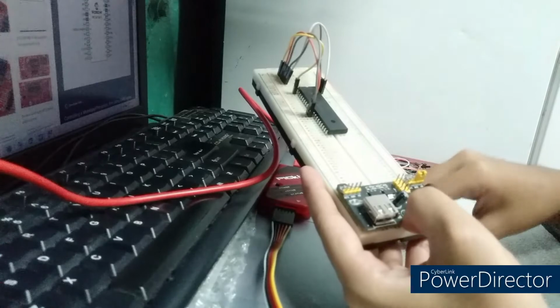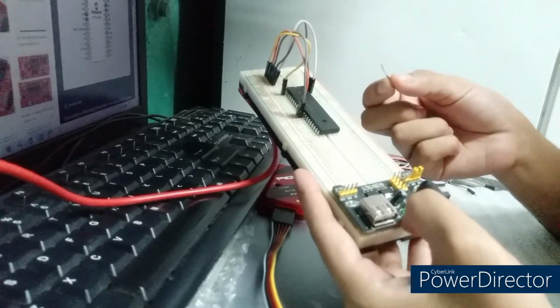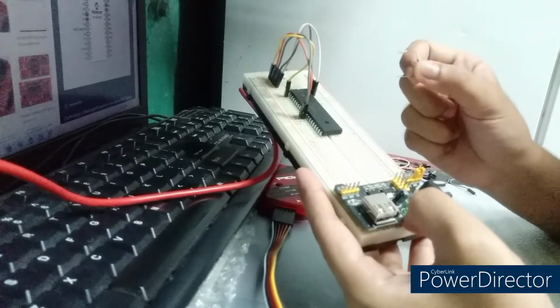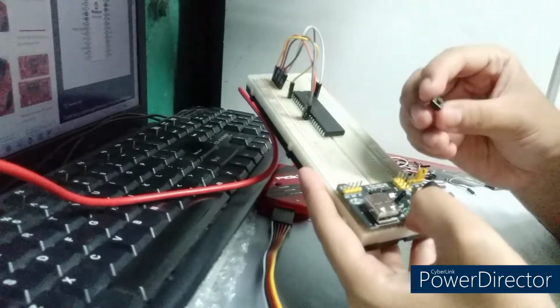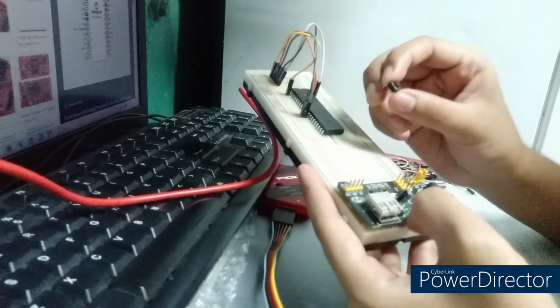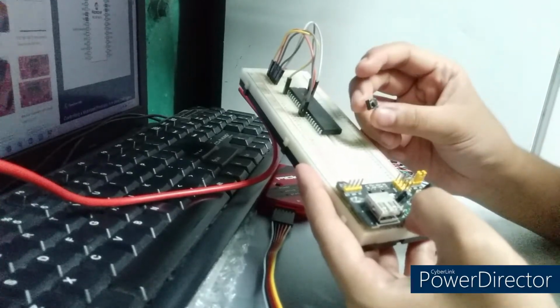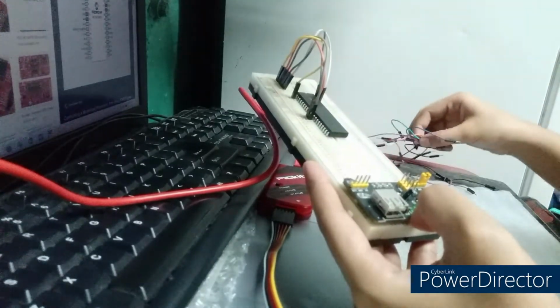We will be needing an LED, a 220 to 360 ohm resistor, or maybe just at least 1K, okay? We will also be needing a tactile switch. A rocker switch can be good as well, but a tactile switch will be better for our simulation since it will be mounted to our breadboard. And then we will be needing our connecting wires.